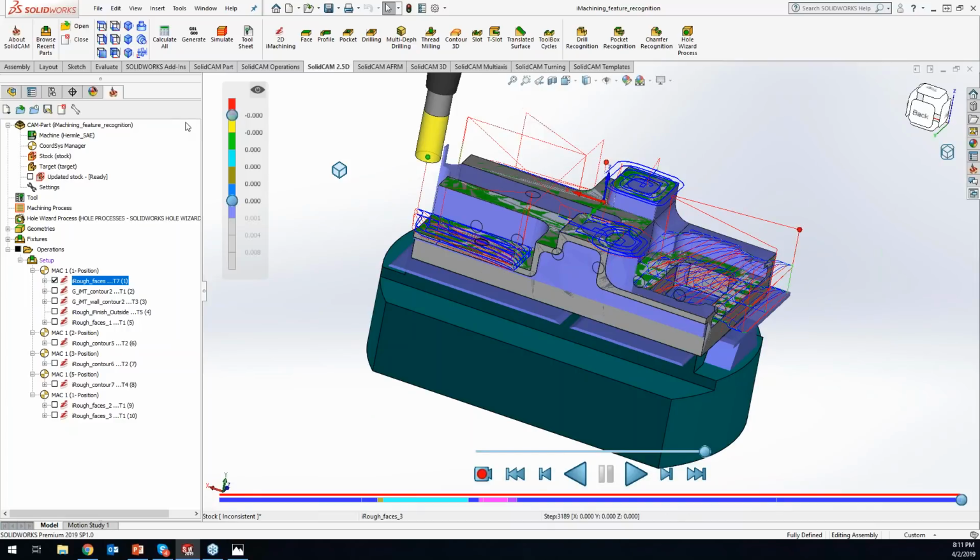And like I said, you have the full ability to come in here and bring it to different parameters. So let's say I just want to see everything between this zone right here. So it's going to show me just anything that's gouging, anything that is oversized, or that is right on size. And you can adjust any of those values as well by clicking on the text of the value and adjusting it to whatever you need.